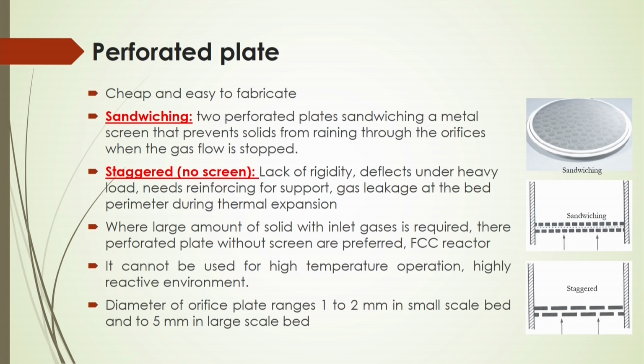And for staggered without a screen, you will see some disadvantages here. In this case, there is a lack of rigidity, and it deflects under heavy load. So in that case it needs reinforcing for support, and there is gas leakage at the bed perimeter during thermal expansion. So, these are some characteristics of the staggered perforated plate without screen. Here see staggered, these holes are unevenly distributed, through which the gas is flowing through these pores or orifices.